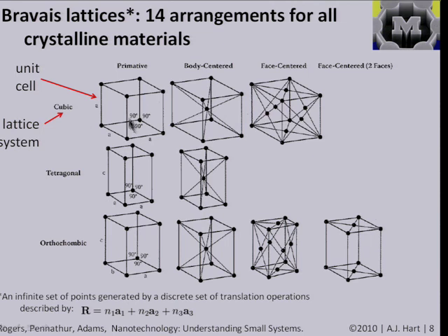You could say perhaps the simplest Bravais lattice is a simple cubic lattice, where it's just like atoms in a cubic grid, and the atoms exist at the corners of the cube. And if you imagined taking 8 atoms and slicing through them, so you had an 1/8 of each atom at each of the corners, that would define the unit cell. So the idea of the unit cell is the smallest repeating unit. So you can take a whole bunch of unit cells and you can stack them up like stacking up little building blocks, and you can make a larger and larger crystal.